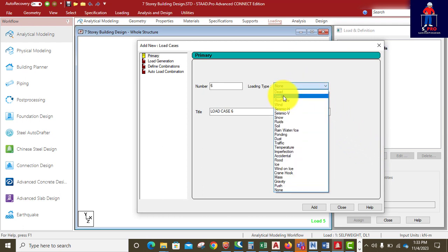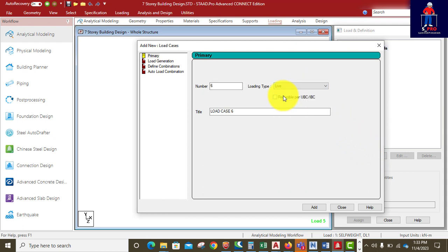It is a live load. I explained in our last class that the water load is a live load because at some point there won't be water in the tank, at some point the water will be halfway, and at some point the water will be full. So it's a live load, it comes and goes. It's not a permanent load.